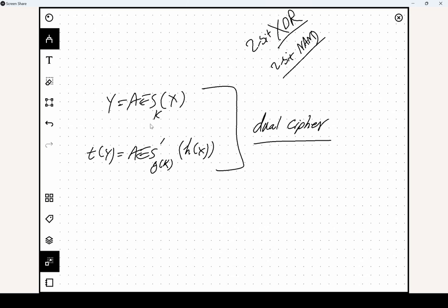I mean, they are completely the same with the same guarantee, but then you just map the inputs and the outputs. I mean, the inputs, of course, the keys should also be considered as an input of this implementation, of this design. And this is the same when you apply the isomorphism at the start of the Galois, of the tower field implementation, what David Canright did.